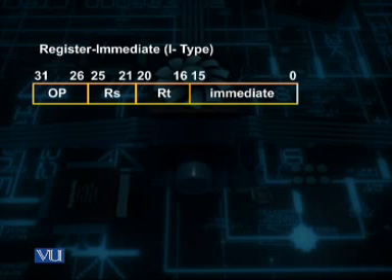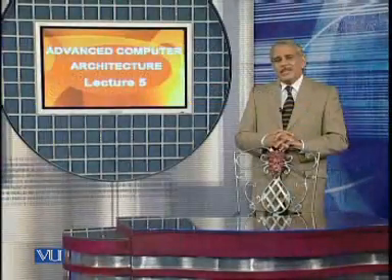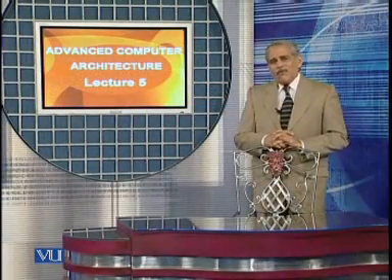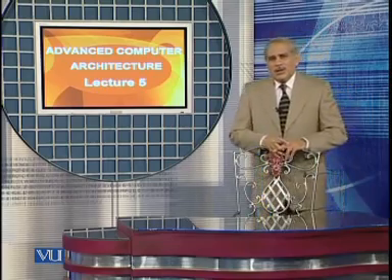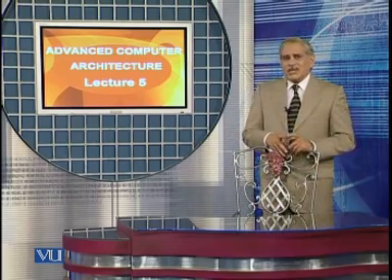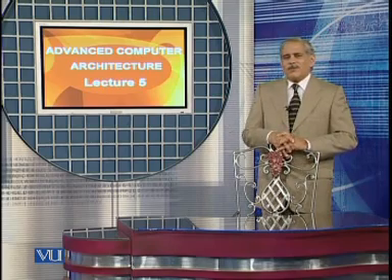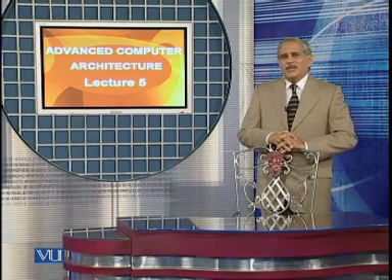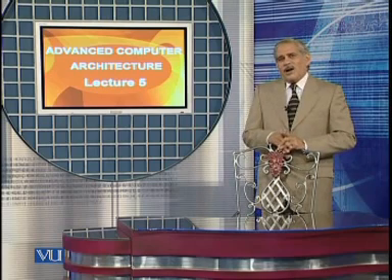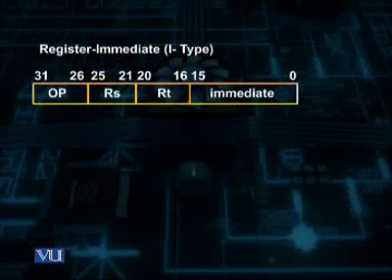The field RT over here in this instruction is used for the destination location, instead of using this for a temporary register, as in the case of the second address field in the register type instruction, which was RT. But this location is no doubt RT, but actually it is the destination register in case of certain instructions. Again, looking into this, the same instruction word format can be used for immediate data type as well as for load and store instructions.